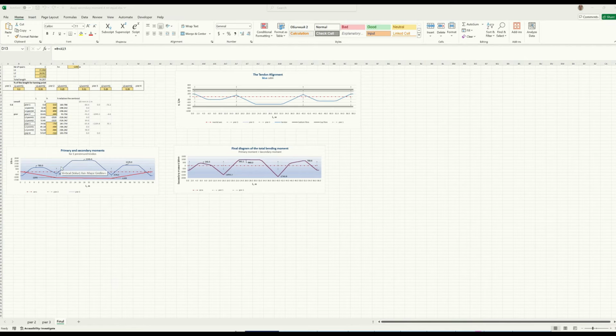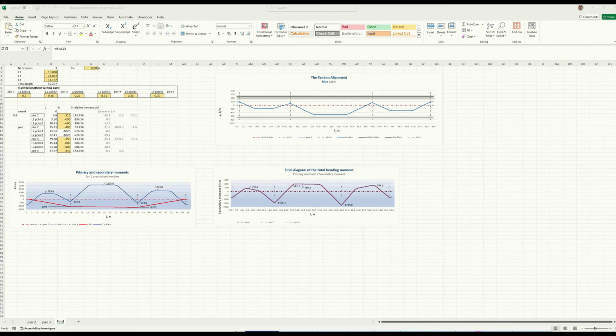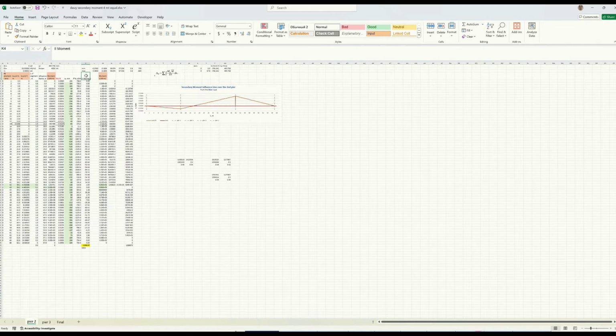What I did, I put there my spans and height of the section. Then I did the procedure that I described before in MIDAS Civil and got the following figures. Here I got the figures from 1 radian rotation, divided by the stiffness and multiplied by primary bending moment.